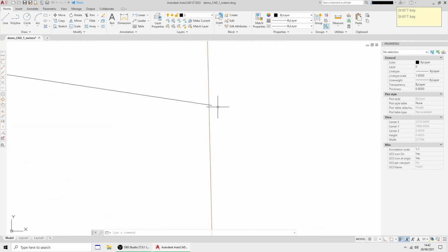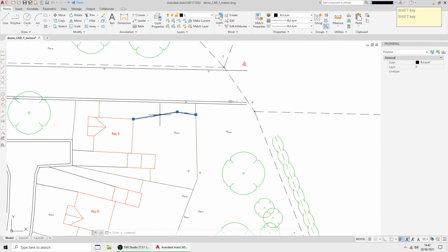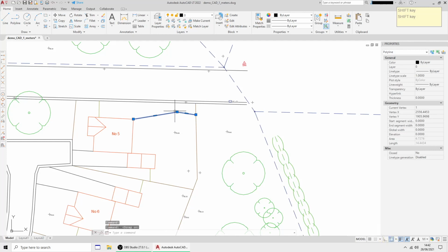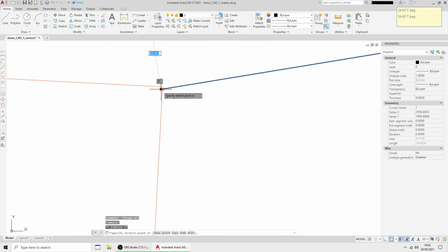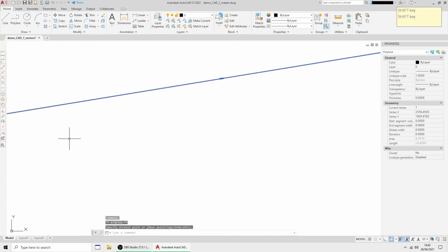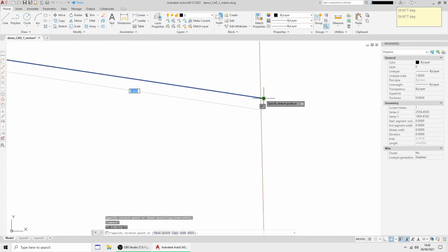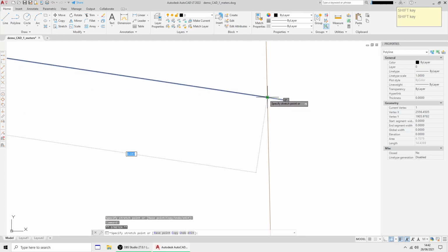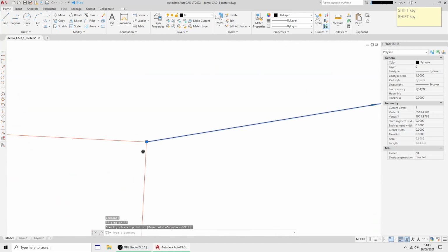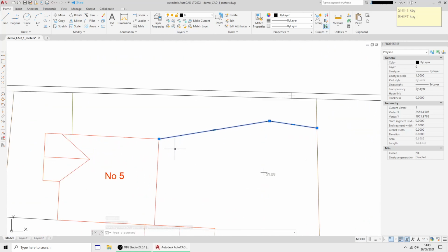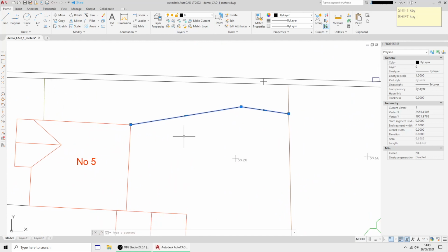And I've missed this one as well. But if I had my snap settings active, I can grab that and lock it properly to the corner. And grab that and actually use its own line as a snap point now. It's accurate, nice work, and that's what you should strive to do really.